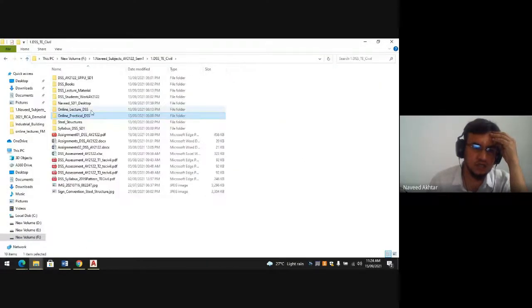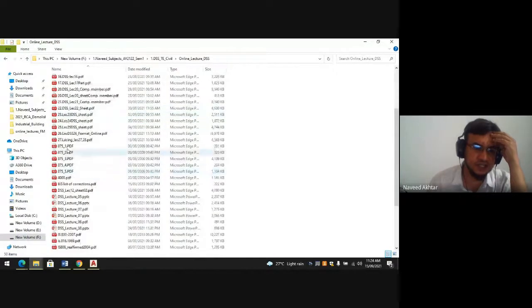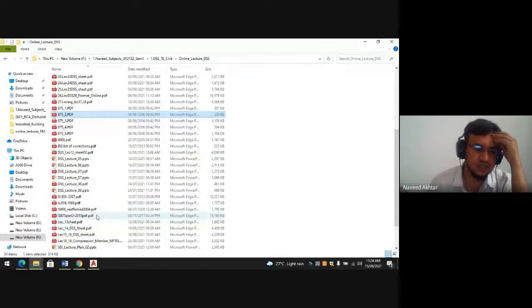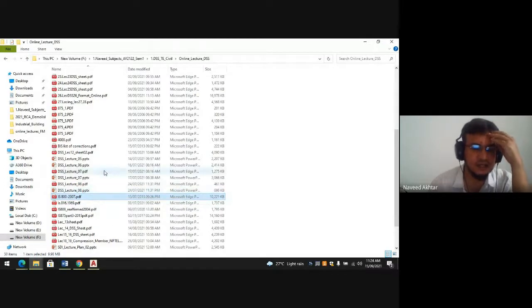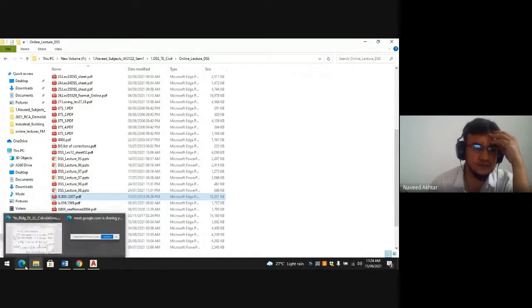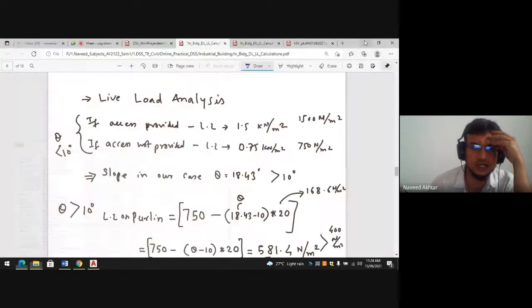In the online lectures, IS 875 Part 1 is for dead load, IS 875 Part 2 for live load, IS 875 Part 3 2015 for the wind load, and IS 800 2007 for the design of steel structure guideline. So we have already gone through all these IS codes, and based on IS 875 Part 2 the live load analysis is done.